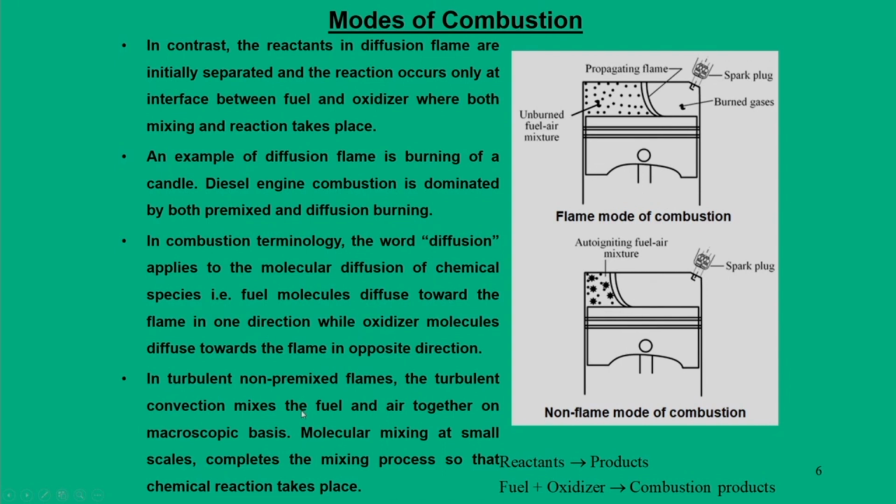And moving further, there is another concept of turbulent flames. In a turbulent non-premixed flame, the turbulent convection mixes the fuel and air together on a microscopic basis, and in the small molecular scales, the mixing process occurs in a very small domain or thickness, and that is where the chemical reaction takes place.